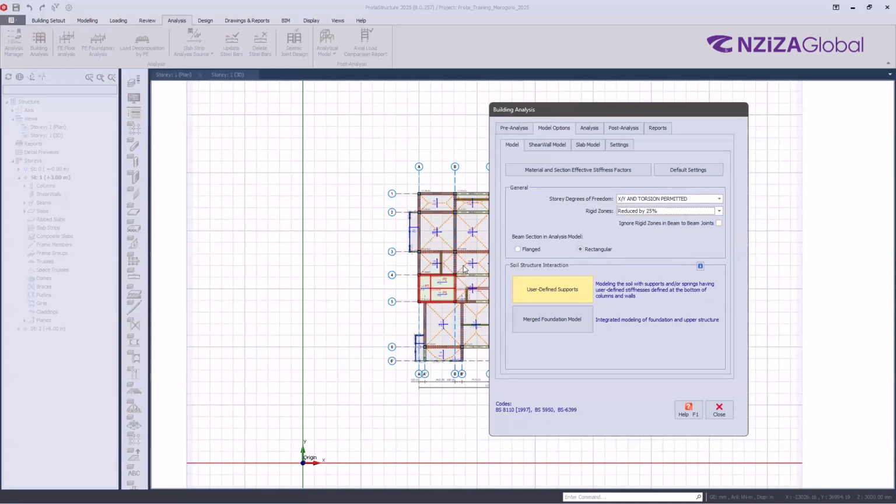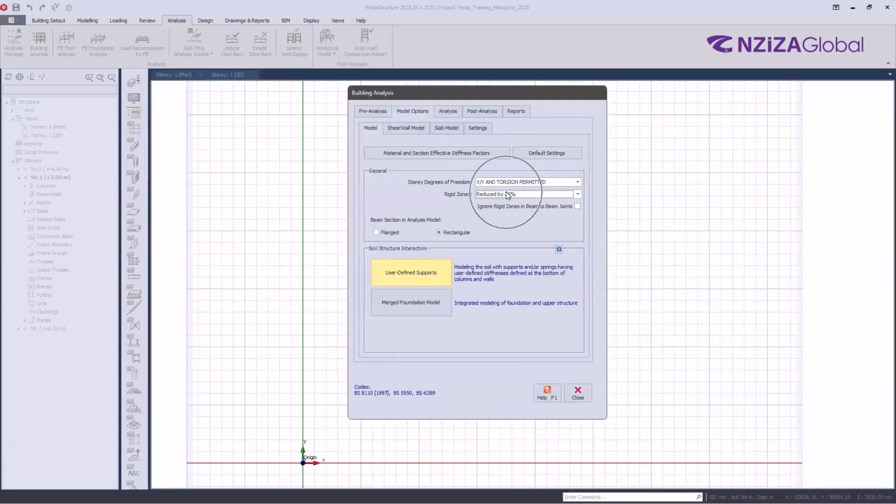But let's suppose that maybe you were dealing with steel members, like designing a warehouse where the column is steel and the beam is also steel. Between the column and the beam, maybe you connect using bolts and so on, so there is no rigidity between the column and the beam. In that case, maybe you can use none. So that's how I can explain this rigidity zone.